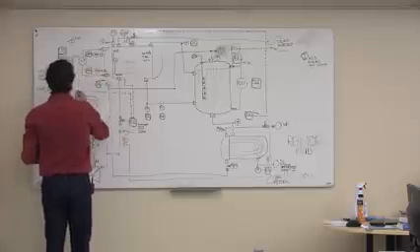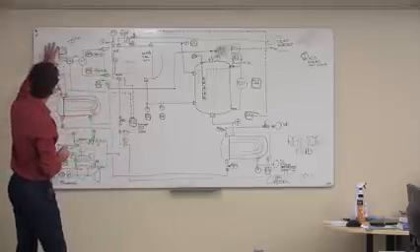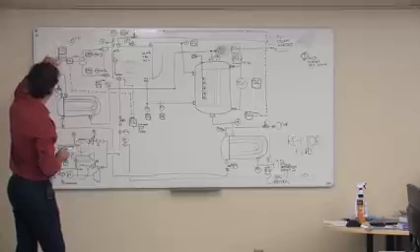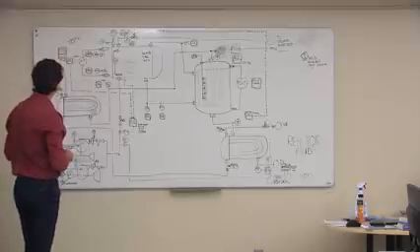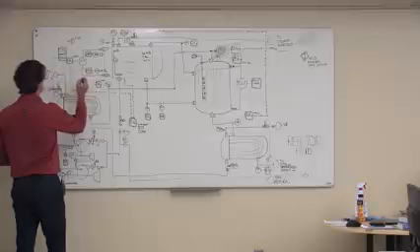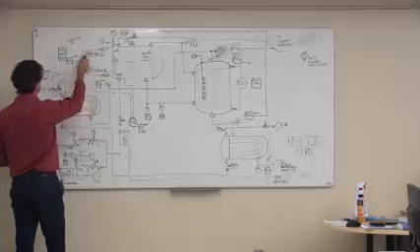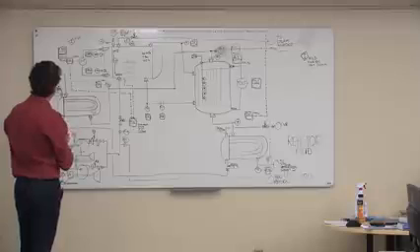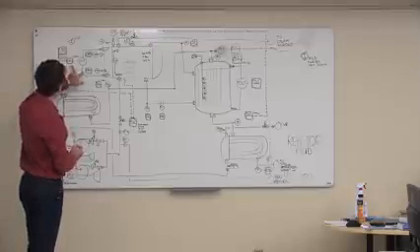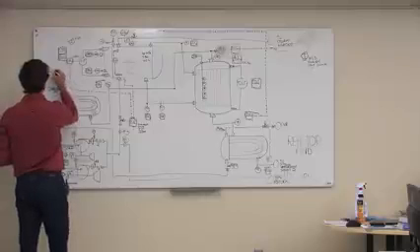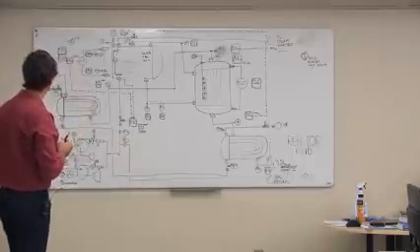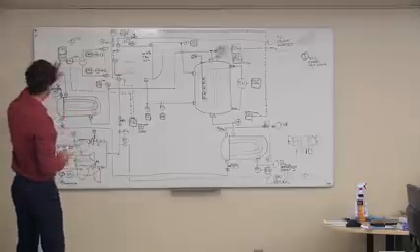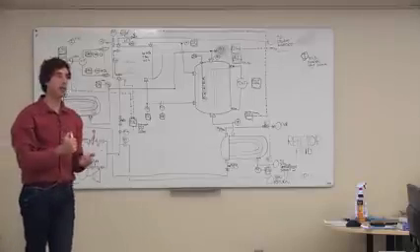And maybe what you would do is actually do the start-stop of the pumps based on these level switches instead of the transmitter. You could do it on both, actually. So you could easily, in the software, if either one of those basically goes low level, like that, if either one of those low level measurements is detected, then we're going to start the second pump. So whichever pump is off, we're going to just turn on.